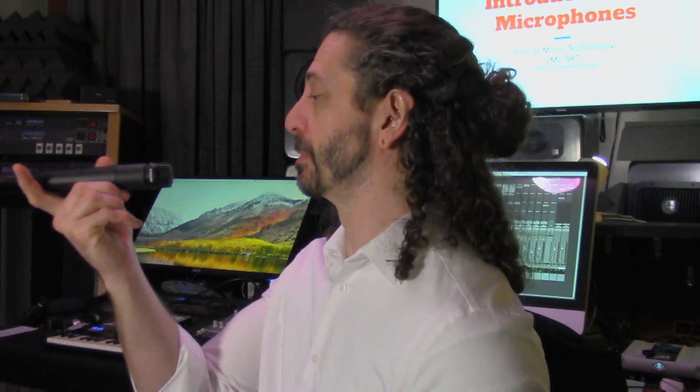So if I had a Shure SM57 and I'm very close to the microphone like this, about 6-8 inches away from the microphone, this is probably going to exhibit proximity effect. If I take the same microphone though, and I move it maybe back 2 feet or so, we're going to find if it does exhibit any proximity effect, it's significantly less than it was when it was much closer to me. Now again, we could think of this, is this a good thing or a bad thing? Well, it's just a thing.